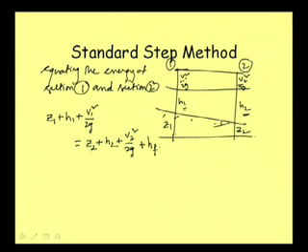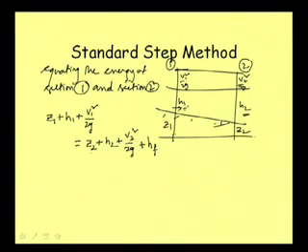In between there may be eddy formation if there are some changes in the channel pattern, velocity is also dropping significantly from V1 here to V2 here, and because of that change in velocity there may be another kind of loss that we call eddy loss. That is why that loss was also added here as he.